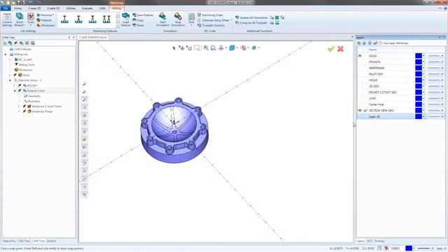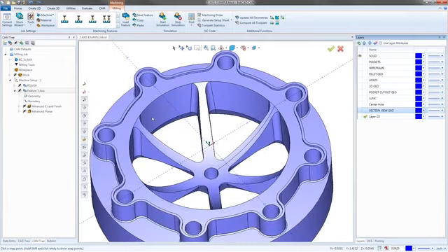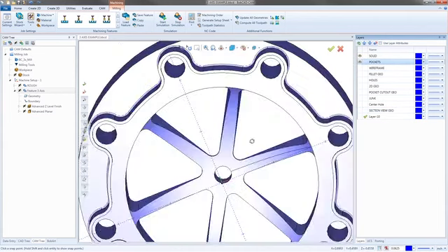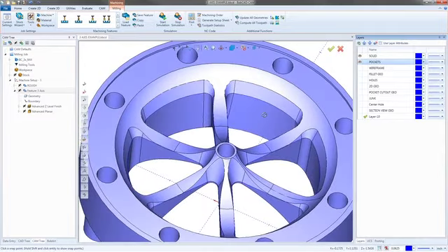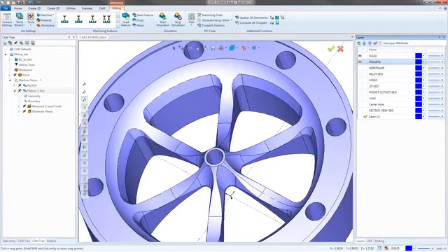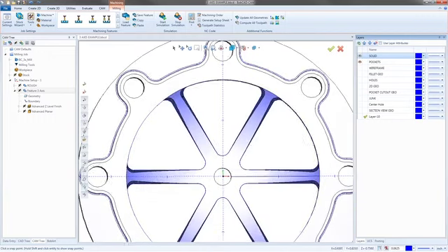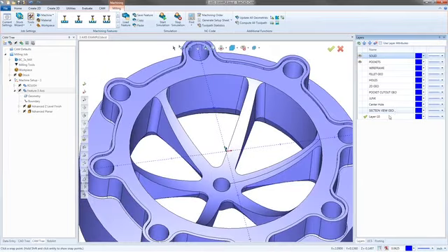All right, so now if I turn off this section view layer that I made, we're back to this. So the last little cut I want to make, I'm just going to do these inside pockets here. I have some geometry set up for the pockets if I could find it. Where the heck did I put it? Let me turn this one off. Okay, there's my pockets. So the only thing I'm worried about is if those pockets are big enough, and they are not. So I'm going to extract some edges on here. So I'm going to make a new layer. I'm going to call it bounds because this is going to be for a boundary on here. Give me 1 second. Let me just clear these things away.